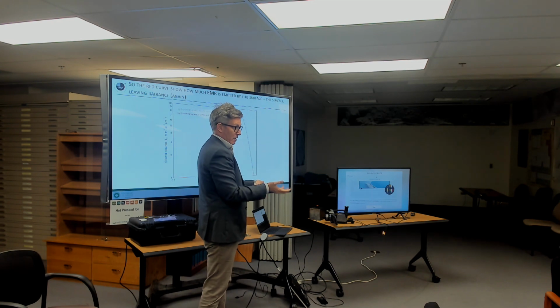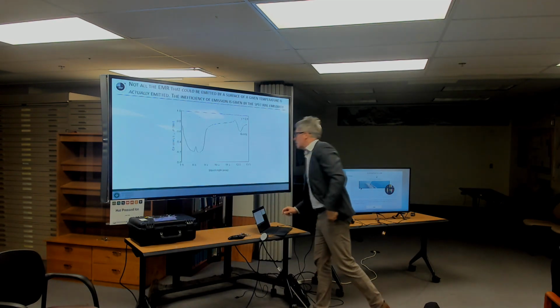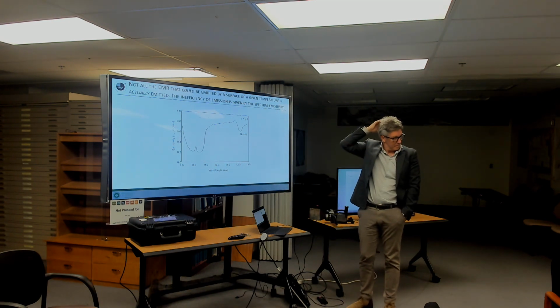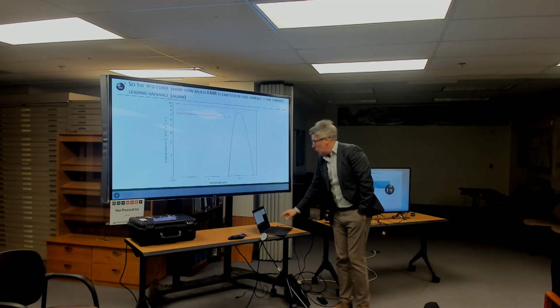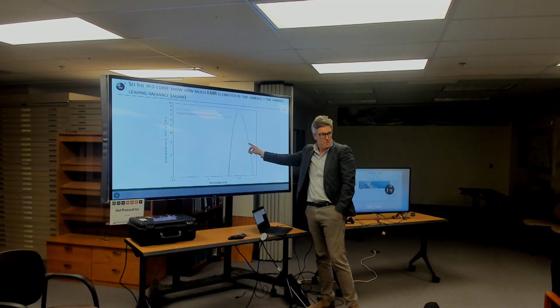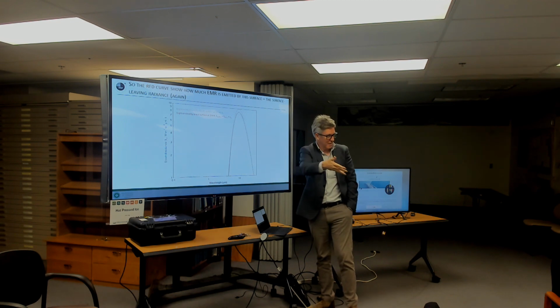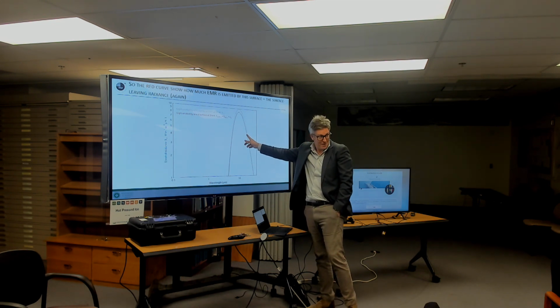So if you wanted to do it for a real target, instead of using 0.9, you just use that curve in a column in your Excel spreadsheet. Right. Okay? So this is the energy that could be radiated from something at 300K if it were a black body, but it's not a black body. It's a real thing with a real emissivity. I'm just going to assume the emissivity is 0.9. It could be anything. And I'm going to multiply every point on the grey curve by 0.9, and that gives me the red curve. Right?